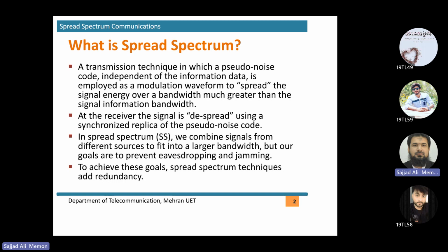But for that, we need something that keeps our information either in phase or in amplitude of the carrier. So if there is a carrier, there must be some frequency. So we have to keep users distinct from each other, either in frequency or in time. Then we have frequency driven multiplexing or time driven multiplexing. However, in 3G, we have WCDMA, that is code driven multiplexing. That means we just separate users in code rather than in time and frequency.